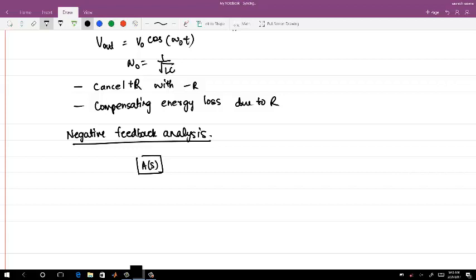So we have a gain A. Let me just write it here. This is positive, this is negative. If I give a sine wave at the input, say you start at time t equals 0 with 0 here and give a sine wave at the input, then the wave appears here, it's multiplied by the gain, and it depends what the gain is at that frequency in terms of phase and everything. Because I am giving a single frequency, you need to see the phase and the magnitude gain and what you get at the output.